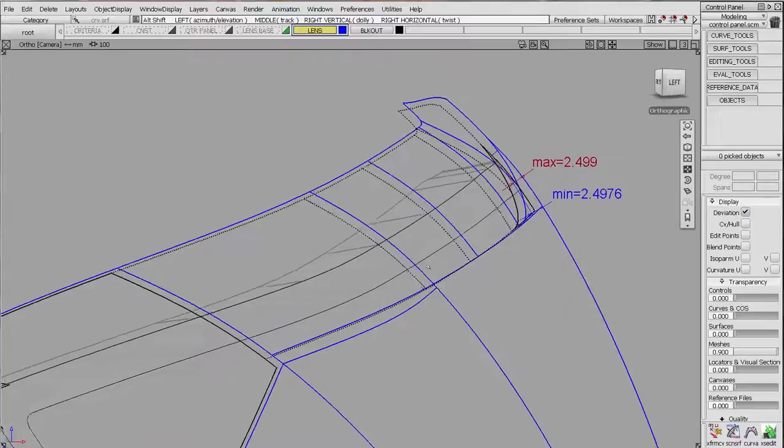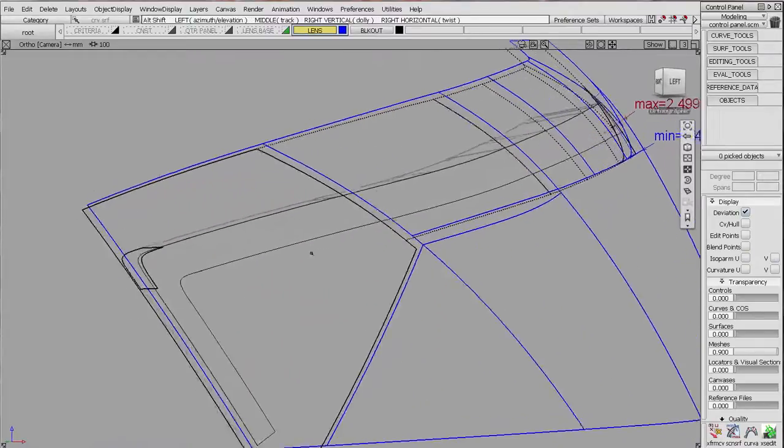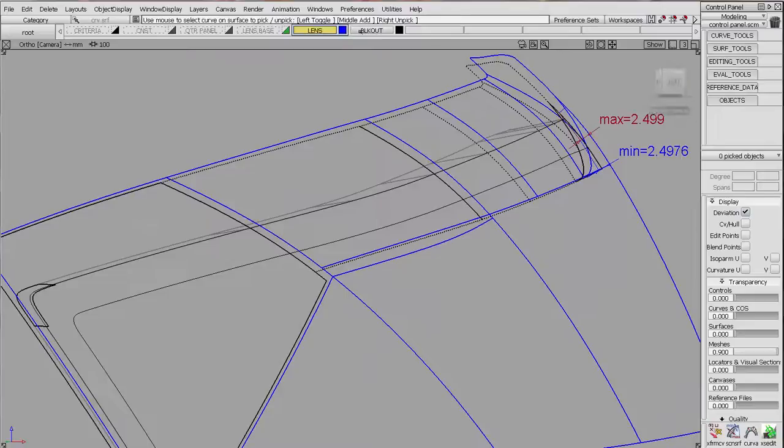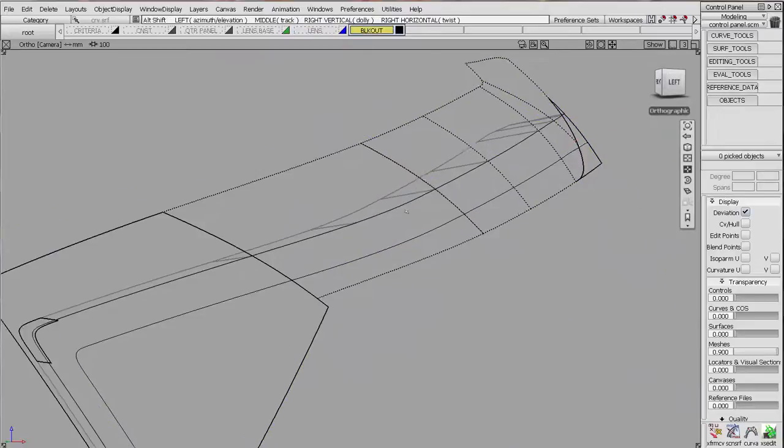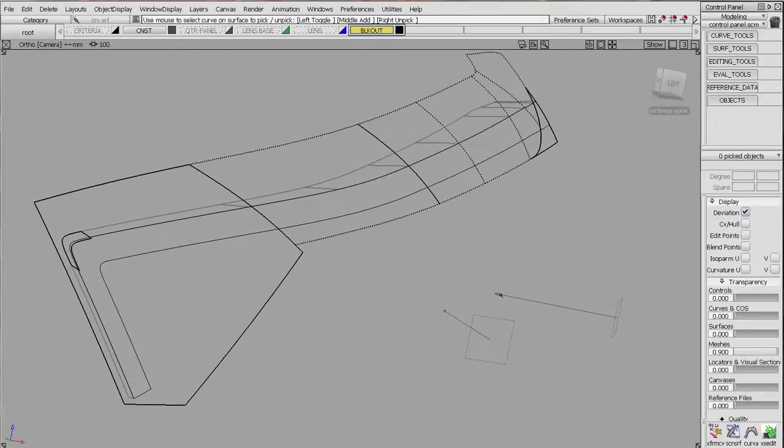Now what we need to do is construct that draft surface. We're going to be constructing that draft surface from this intersection line. So if we temporarily turn our lens off here, let's make that. To make our draft surface we need our die vector.